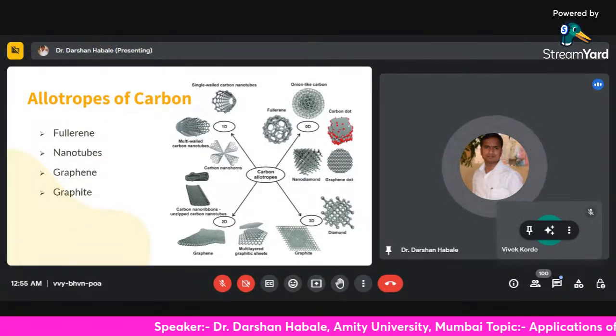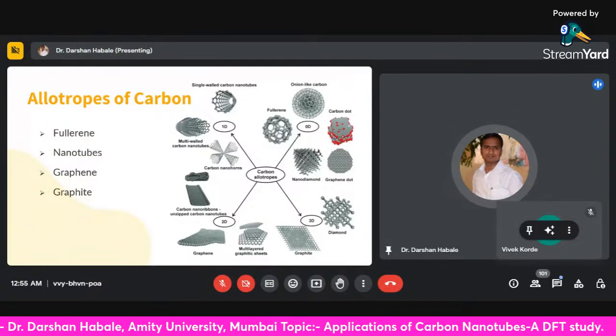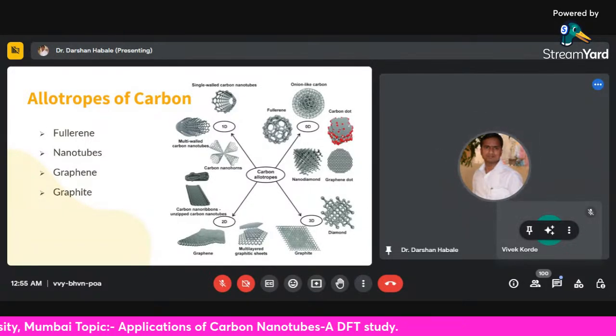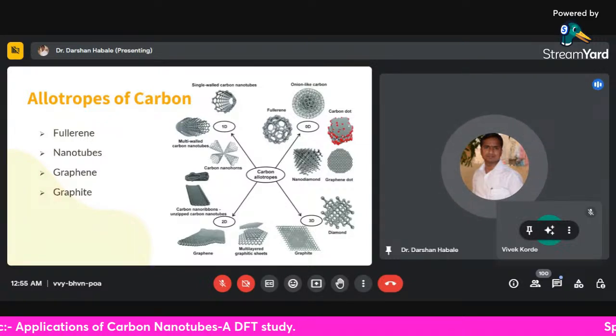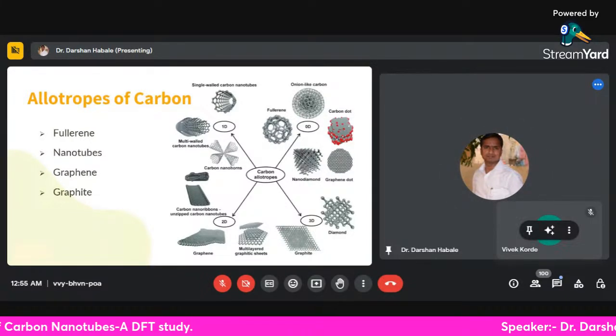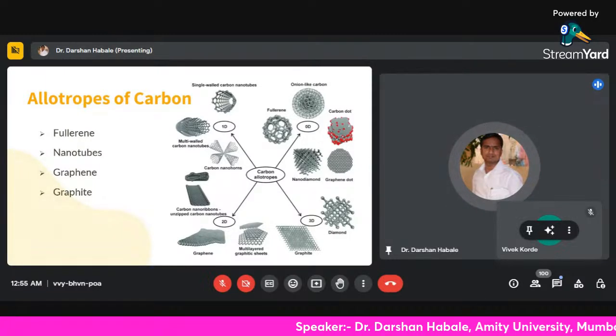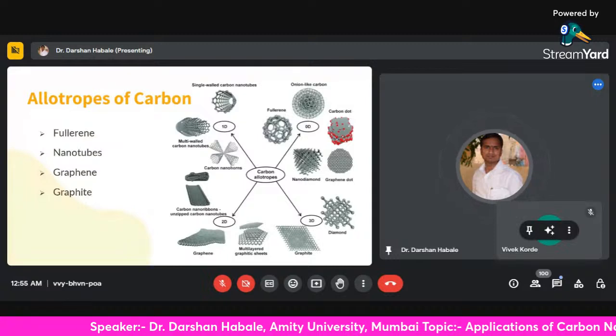Structural flaws introduced into the lattice during growth or by physicochemical treatment can dramatically impair graphene's characteristics and the performance of graphene-based devices. Melt intercalation, in situ polymerization, and solution mixing are the most common techniques for incorporating graphene into polymer matrices.